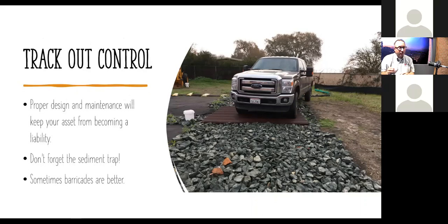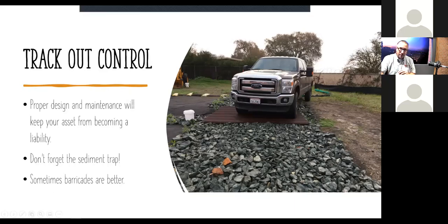And the other thing that is often left out of these is to have a settling basin or trap or a place you can wash sediment out into alongside of it. The reason for that is, again, to control your flow, but the other is so you can maintain it. You can take a fire hose then, wash out that rock and those grizzlies and get the sediment down into your basin, and that'll make it so much easier to maintain it. So you really want to design these and position these in the right places.